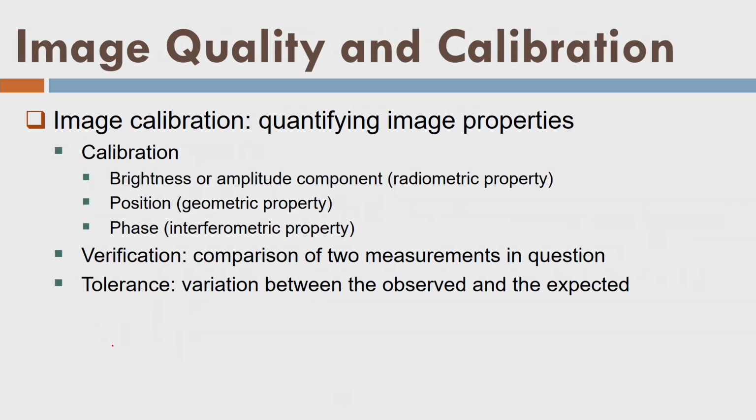So let us say that you have received a radar image and you have removed the speckle. Now you want to calibrate the radar image, because the calibration will give the value of the digital number at a certain point. Take a reference value. Remember the reference value concept? A reference value is an ideal value. For grass I have a reference value, for a stone I have a reference value, and for some other material, let us say sand, we have a reference value.